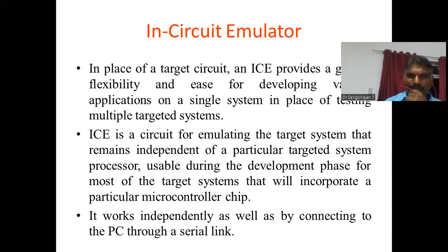Then in the place of a target circuit, this ICE, the in-circuit emulator, will provide greater flexibility for developing various applications on a single system in place of testing multiple target systems. This ICE is a circuit for emulating the target system that remains independent. It is independent of a particular target system processor for most target systems, which will incorporate a particular microcontroller chip.